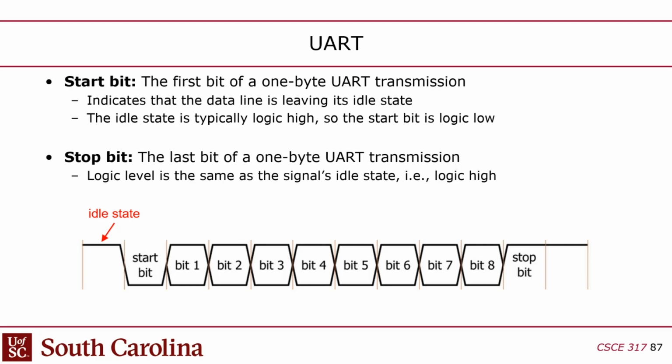The problem is that if the driver changes a bit and it's in a state of change, and the other side is sampling it on the clock edge at the same time, that's going to cause the receiver to go into metastability. So the receiver is going to get an error. It's not going to read that correctly.